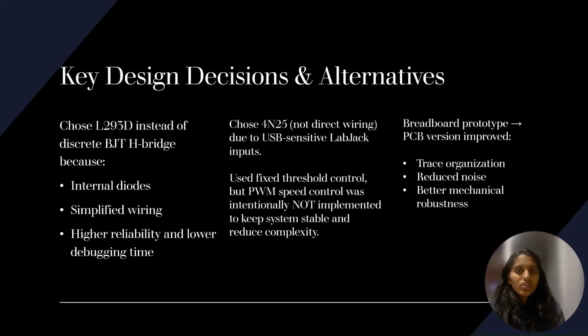We also used a 4N25 optocoupler between the lab jack and motor driver. This protects the lab jack from motor noise and from any possible short circuit on the 12 volt side. Because the lab jack is a USB device, isolation is extremely important.